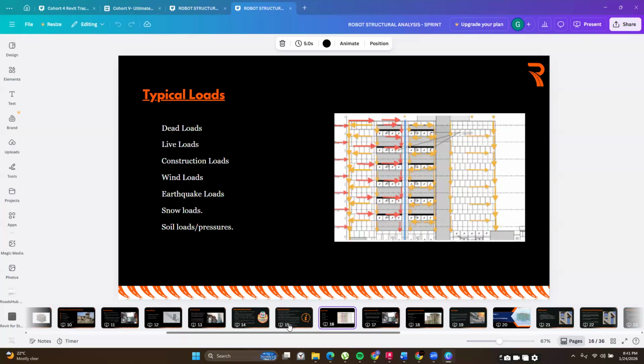So majorly, dead loads are, say, the loads that you expect to be permanent on your structure, or they are going to be, say, more permanent on your structure. They include loads such as the self-weight, or loads or weights emanating from the finishes used on the structure. And then we have the live loads. The live loads are, I don't want to call them temporary, but they vary a lot as the structure is used during its design life. Okay, so in the day-to-day usage of your structure, your live loads are going to vary by a lot.